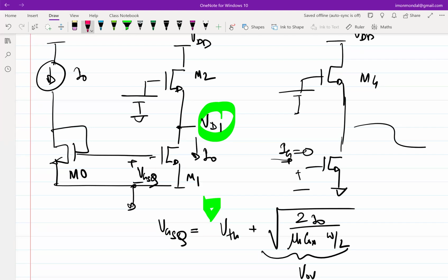so another terminology that is often used is when you see a multiple transistor stack, a designer, or somebody who is maybe interviewing you, will often ask you, who is setting the current in this stack? I have like 5 different transistors, and I know that the transistor equation is mu n Cox W by L (VGS minus VT) whole square. So does that mean if I increase W by L of all transistors or any transistor, the current is going to get affected? Or is there one dominant transistor whose W by L is directly influencing the current?